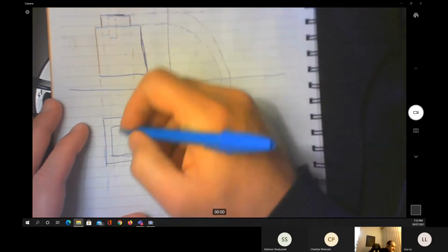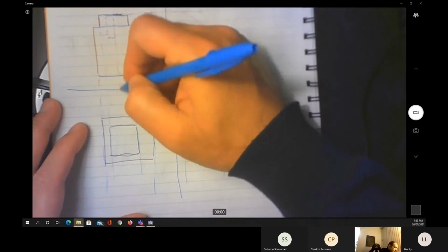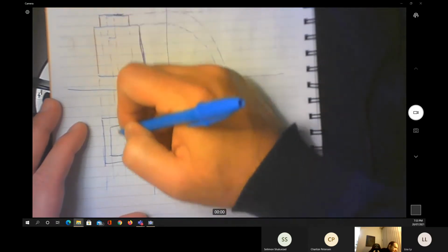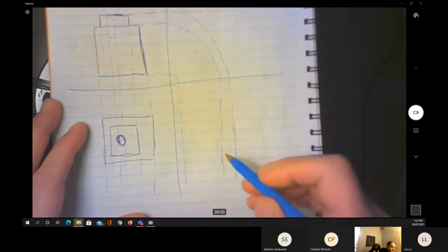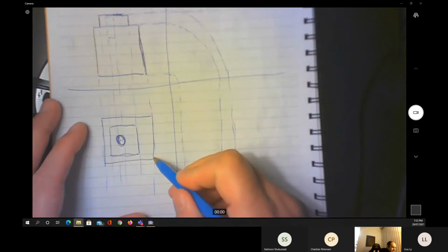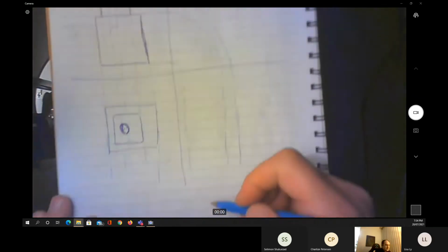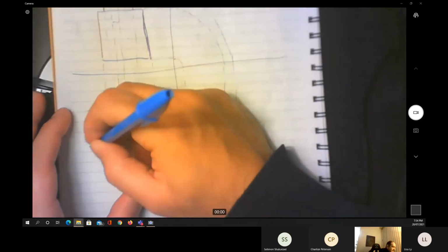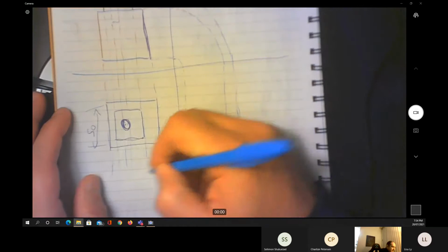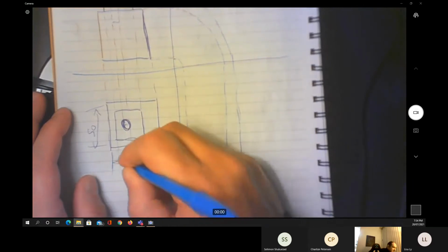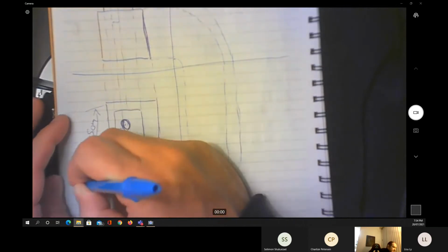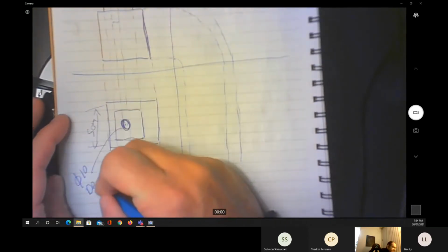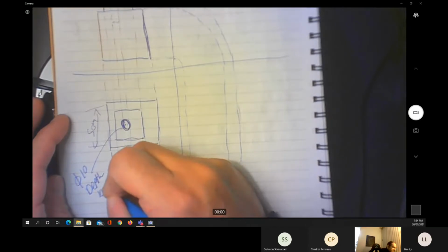Maybe if I'm going to add something. Anyway, I will make it as simple as possible. Okay, and we have a hole in the middle. I don't think we need another side. So I'm going to give you the dimension of that. This one is 50 millimeters by 50 millimeters. The diameter of the hole here, phi, is 10. The depth is 10 millimeter.